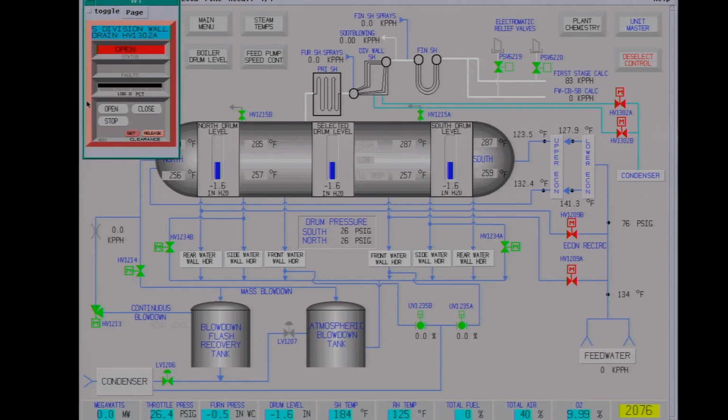I'm going to go ahead and close them. In the past, they've been throttled down and then closed at higher levels. The big thing is to get any moisture out of the steam lines. It seems kind of weird having moisture in steam, but any water droplets can cause water hammering and damage.